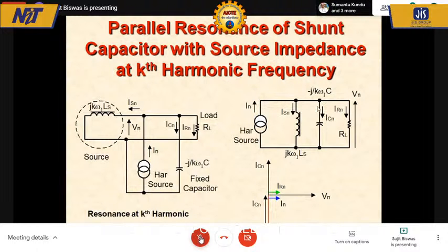They will not exist in the line. That is why IN will be equal to IRN. True, but individually, they will be carrying very high currents. It all depends on the degree of resonance and the damping that's provided. So as a result, your physical capacitor or any effective capacitor can carry a large magnitude of harmonic current in case there is a resonance with the system reactance. This can really kill your system.